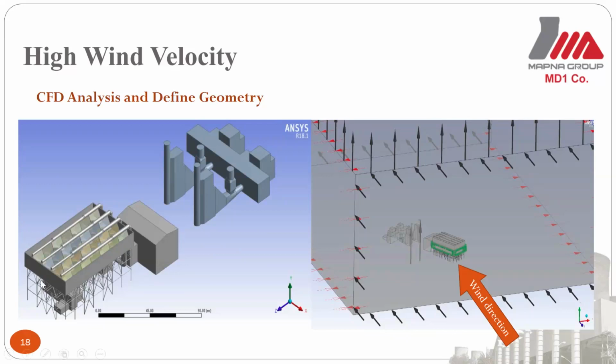As you can see, the 4 and 7 ACC modules, 2 boilers, and the steam turbine hall building. The right shows the computational domain, which is much larger than the ACC plant. This was done to prevent the effect of the external boundary condition in the vicinity of the ACC.